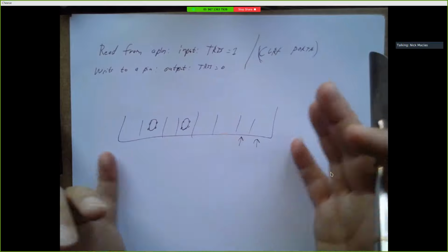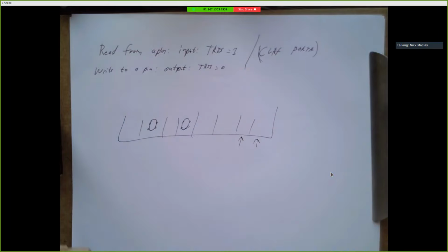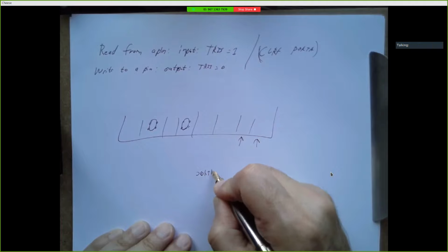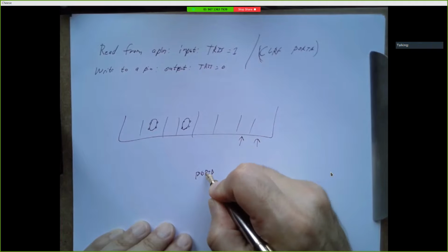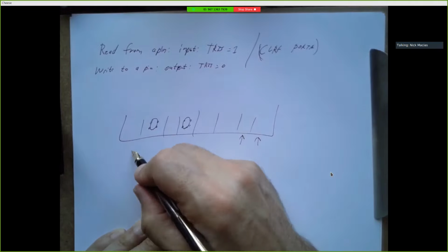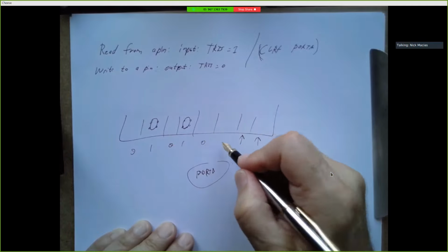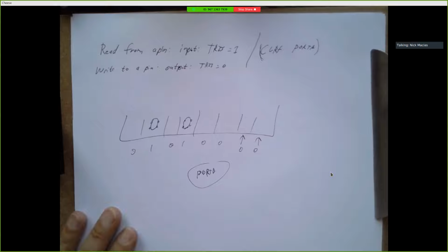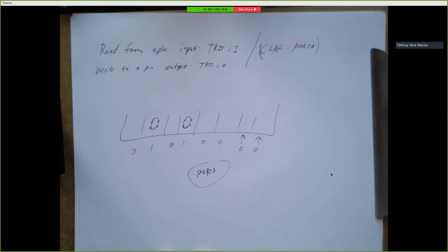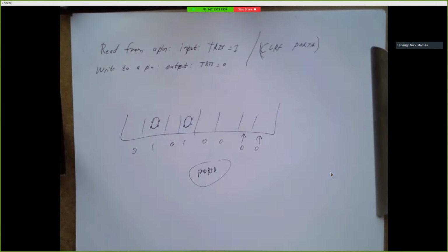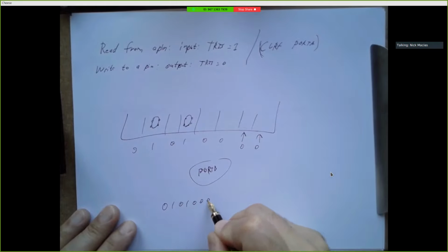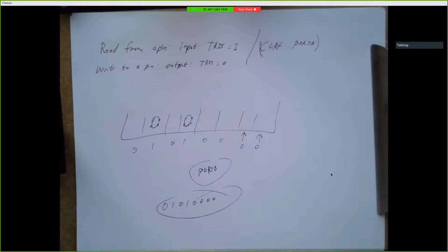Okay, so this is all hooked up to a microprocessor, and you can read from, say, port B. And when you read from port B, you get 1s and 0s telling you whether there's a car in each spot. So I'll set up port B and I'll say let's read from these two locations, and I'll copy it into my W-reg. What is my W-reg going to be equal to? 01010000.